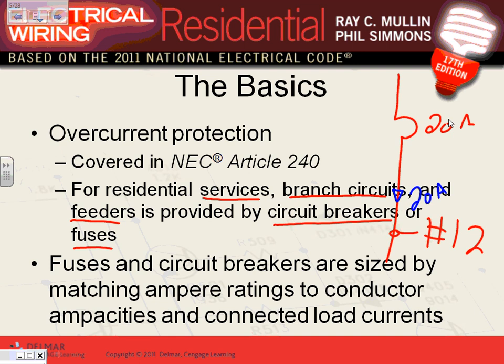Now take this. If I have a short circuit here, here's my equipment here. This is my garbage disposal. Now, Nick, because he's sometimes a troublemaker, he went and shorted. He made a short circuit, grabbed the hot, and tied it to the frame of a garbage disposal, intentionally or unintentionally. So now we have a short circuit. The amount of current that's going to go right in here, I'm going to say 5,000 amp. It's going to keep going all the way to the short, right? You have a 5,000 amp, you shorted, line to ground, you have a short circuit or a ground fault, right? 5,000 amp, yeah. This circuit breaker also has to be rated for 10,000 amp.